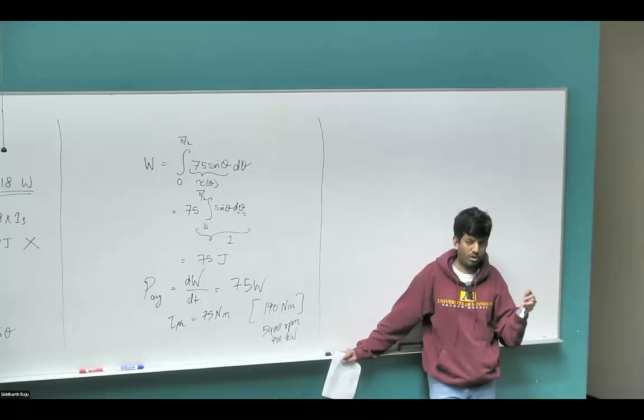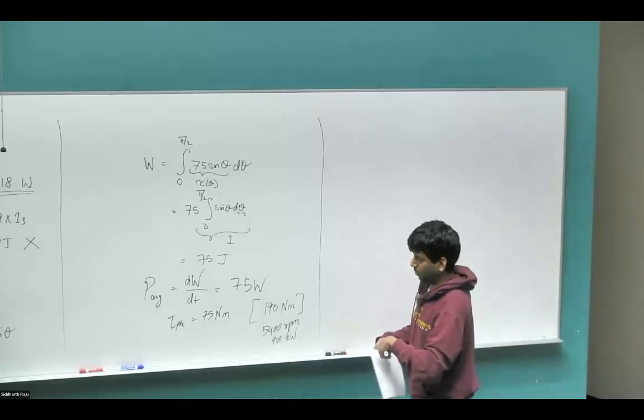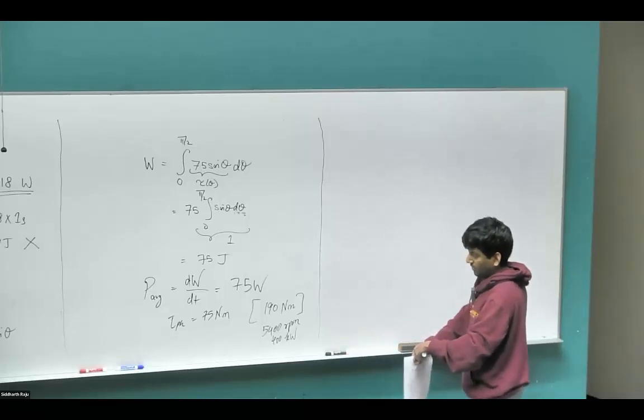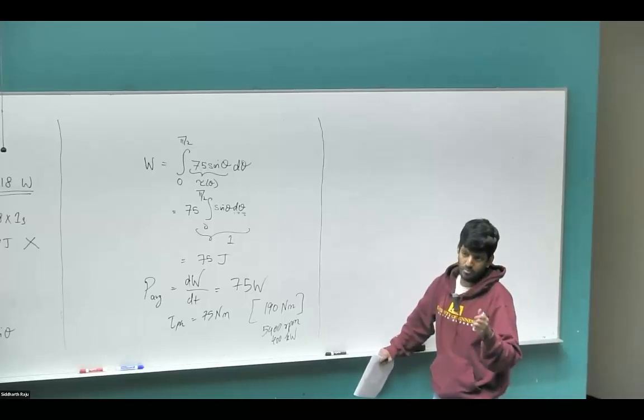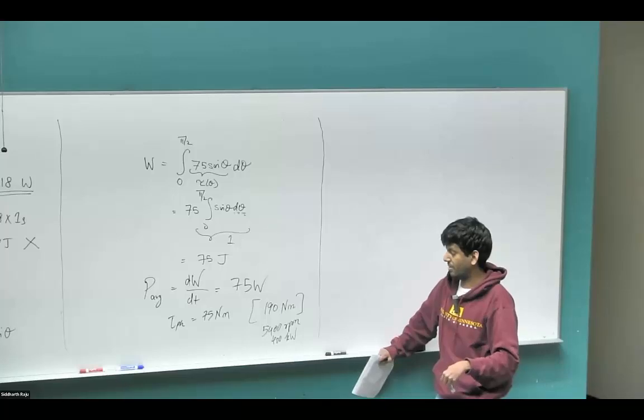So this is one of the biggest problems with going to 100% PV. Something we need to address is to provide that additional inertia, because when there is a sudden load demand that comes up, something needs to satisfy it. Otherwise, the voltage and the frequency would start to collapse in the system. And once it collapses, it could take days to bring it back online. So you definitely don't want that to happen.